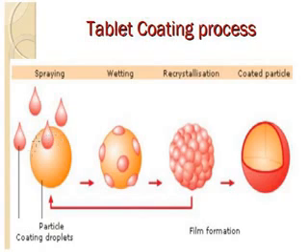Initially these are your simple or conventional tablets. On this tablet we have to spray your coating material in the form of a solution. After spraying, that solution will deposit on the surface of your tablet in this manner, and again we have to spray till the surface of the tablet is completely covered like this.